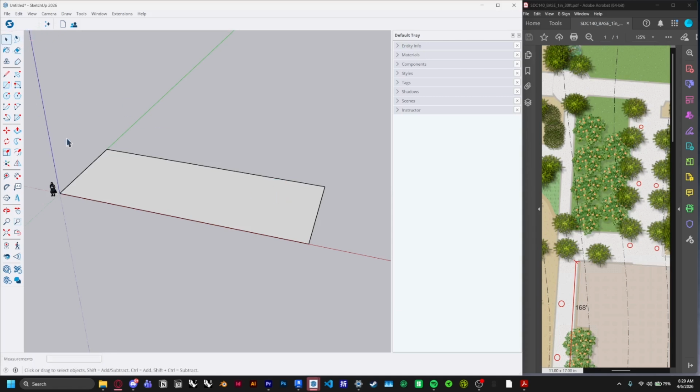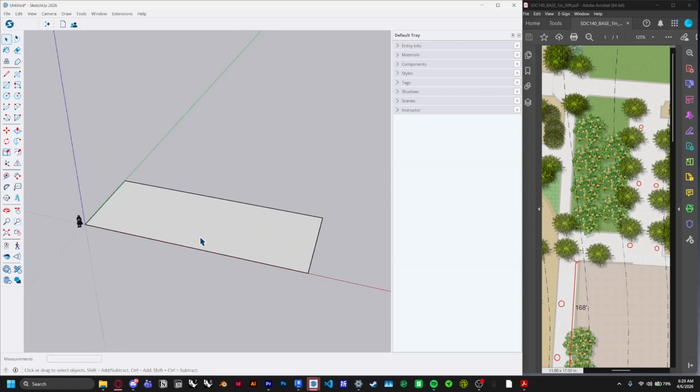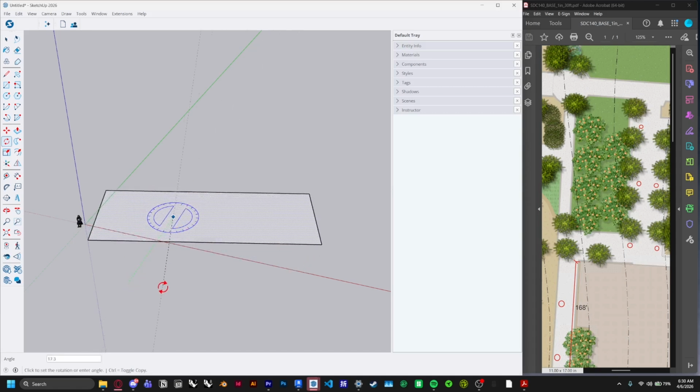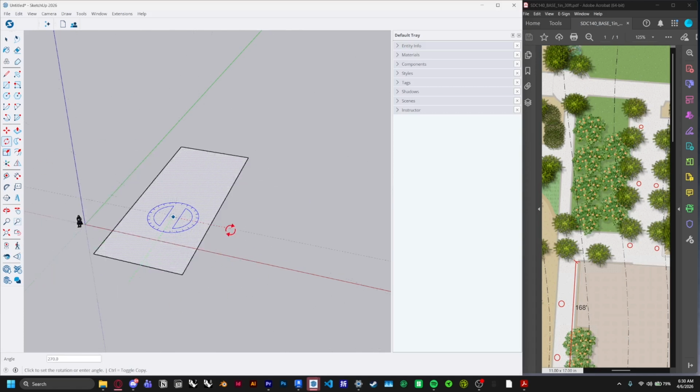But I'll go ahead and rotate it so that you can use the rotate tool. So for rotation, there's 2 arrows pointing at each other a bit down beneath the rectangle tool on the left-hand side again. So go ahead and click that, and when you move your mouse out, you'll have a compass. When you click on the surface that you want to change, you'll be able to rotate around this compass now. So just click it once, and then drag out to a point outside of the box, and then click once, and then you can move the shape along with your mouse. And you'll want to do it 90 degrees.